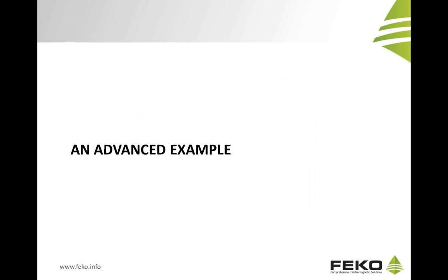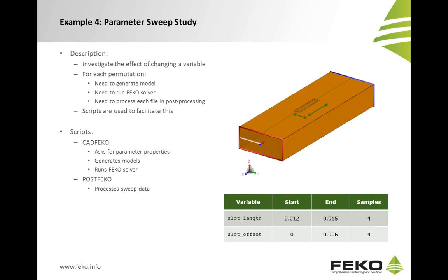Okay, now I can sit back and relax. The final example that I'm going to show you is a little bit more advanced. It also spans across CAD-FEKO and post-FEKO, so it deals with file manipulation and with writing of files and generation of models and then processing of results in post-FEKO. So actually what I've done is write 2 scripts, one for CAD-FEKO and one for post-FEKO, and we will be looking at doing a parameter sweep study for a model.